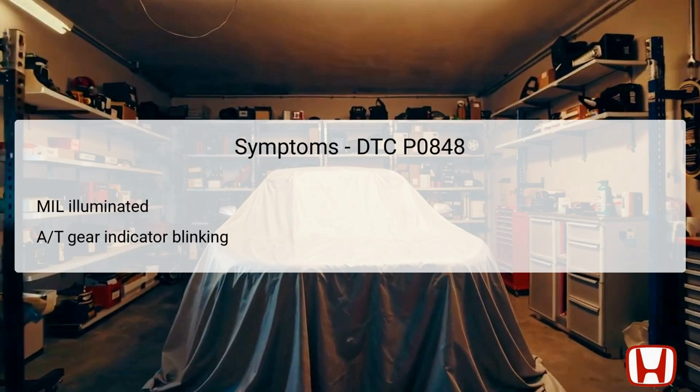Several symptoms can indicate the presence of DTC P0848, primarily involving the vehicle's dashboard alerts. The malfunction indicator light, often referred to as the MIL, will be illuminated when this DTC is triggered. This is the vehicle's way of alerting the driver that there's an issue requiring attention. Additionally, the automatic transmission, AT, gear position indicator will begin to blink. This action directly corresponds to the PCM registering a fault with the signal from the transmission fluid pressure switch.